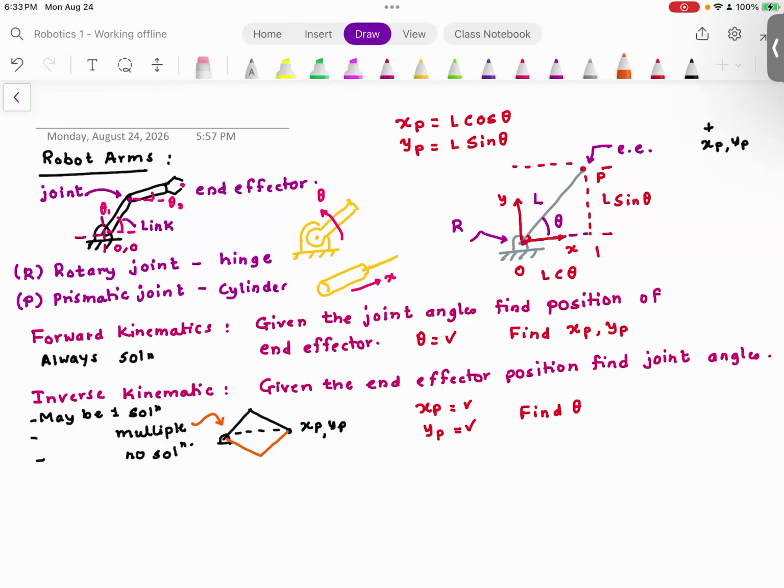So for example, I have the robot, but that robot cannot go all the way over here because there is hardware here, there is a link here that's going to obstruct. So there are regions in the work envelope that the robot cannot physically reach. There are some regions that are on the edge of the work envelope. And when they are on the edge of the work envelope, the robot is fully extended, and then sometimes the robot encounters singularities. It means it gets into something called a lock position. And we'll talk about all this.